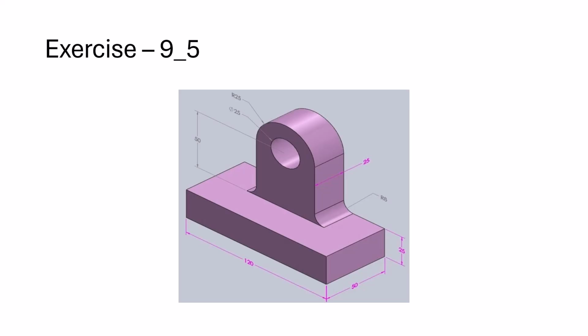In this video, you will learn how to create the given three-dimensional solid by using Autodesk Fusion 360. Here, the base can be created by using the extrusion command. Either you can create this rectangle on the frontal plane or the top surface of the base on the top plane, and you can extrude it for the required distances.